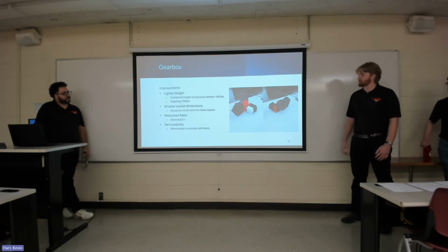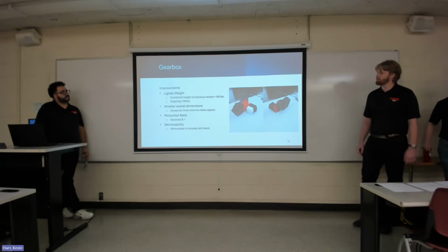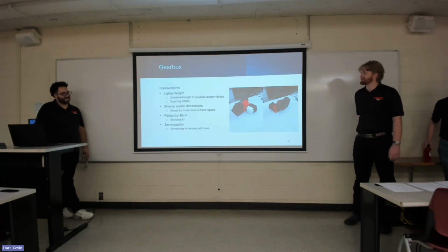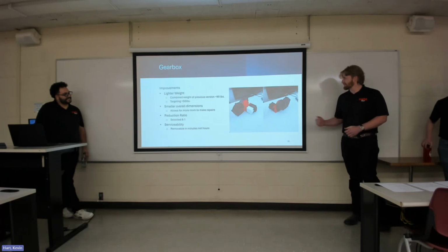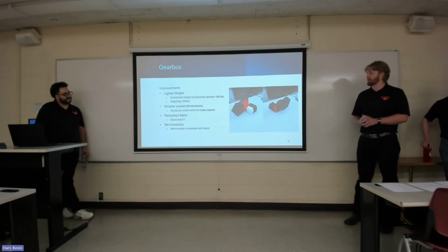As far as our reduction ratio goes, we selected 8-to-1. Previous was 2-to-1, which we kind of just looked into the other day. I'd taken that gearbox apart a bunch of times, and it was designed by a previous team, and I just never really thought, oh, this reduction is horrible. So we did some reduction calculations.